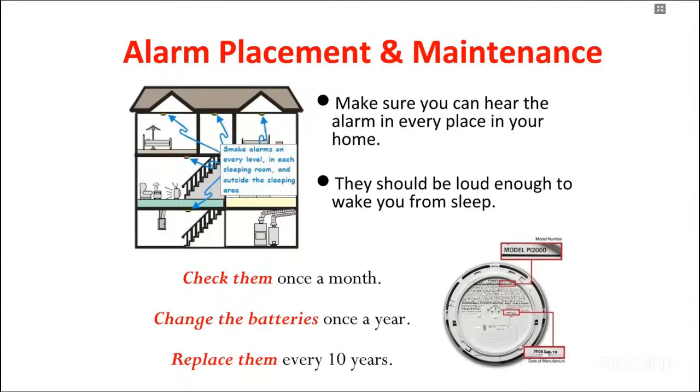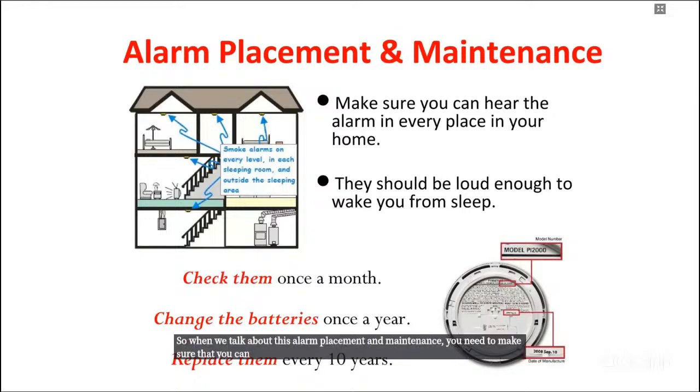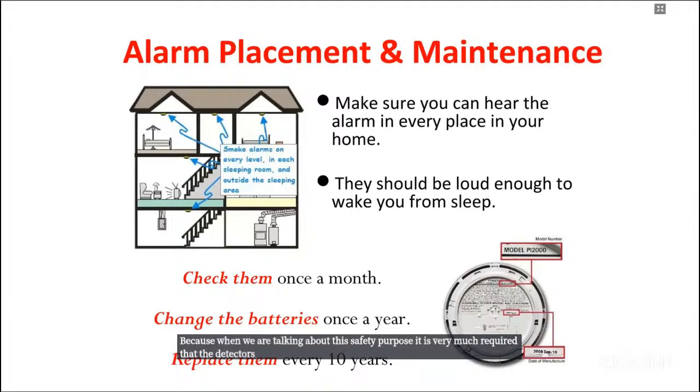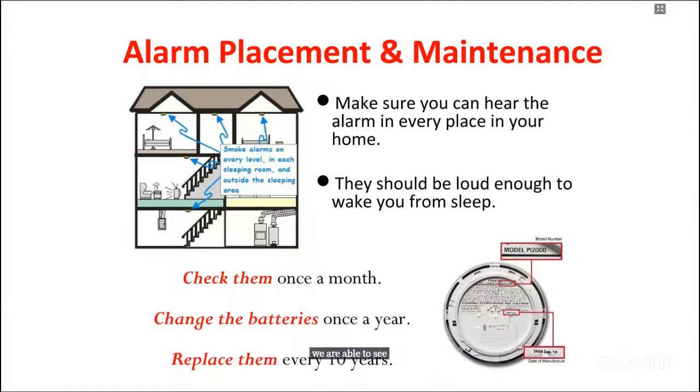So when we talk about alarm placement and maintenance, you need to make sure that you can hear the alarm from everywhere. Because when we are talking about safety, it is very much required that the detectors have to be sensorized. And again, the detectors need to be audible. What type of detector are you using? So when you see the picture on the left, we are able to see that smoke alarms on every level are required, in each sleeping room, outside the sleeping area, wherever it can be, right? They should be loud enough to wake you up from sleep.